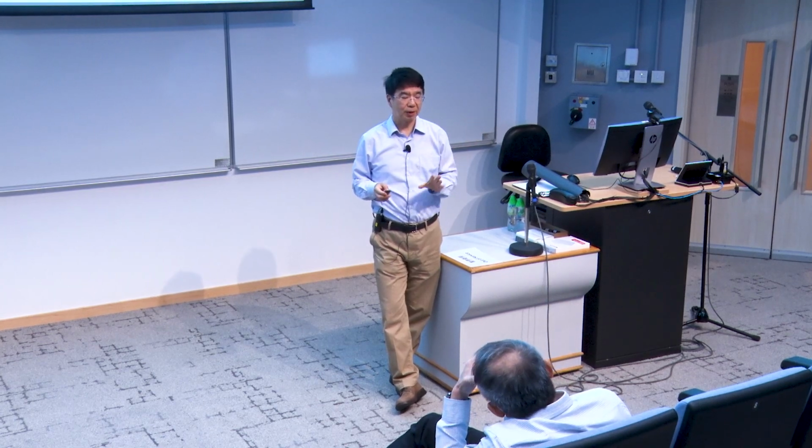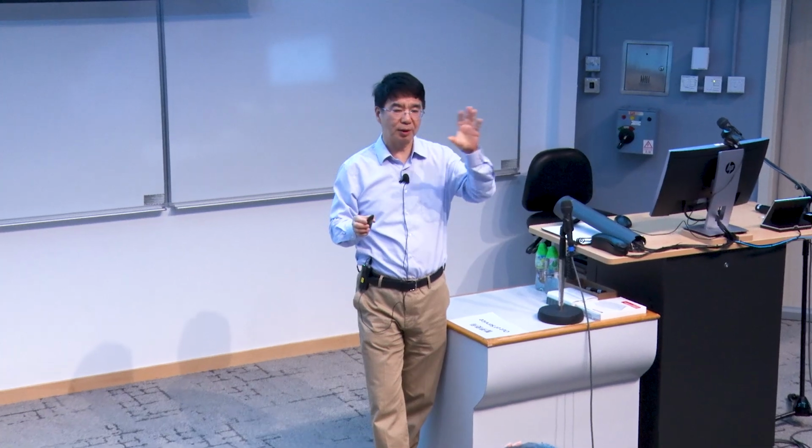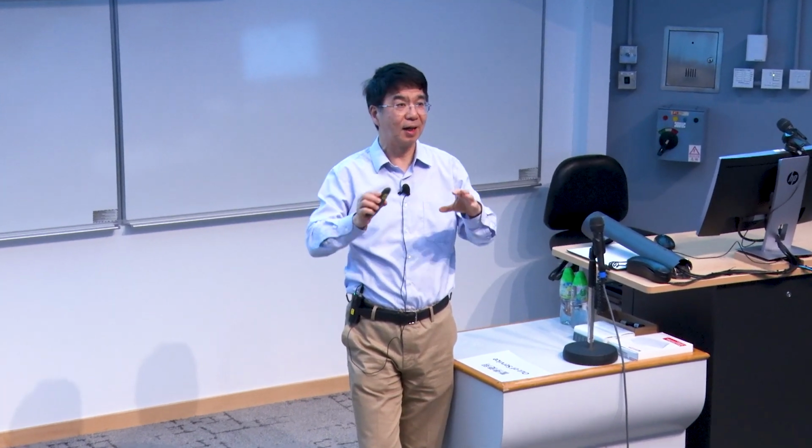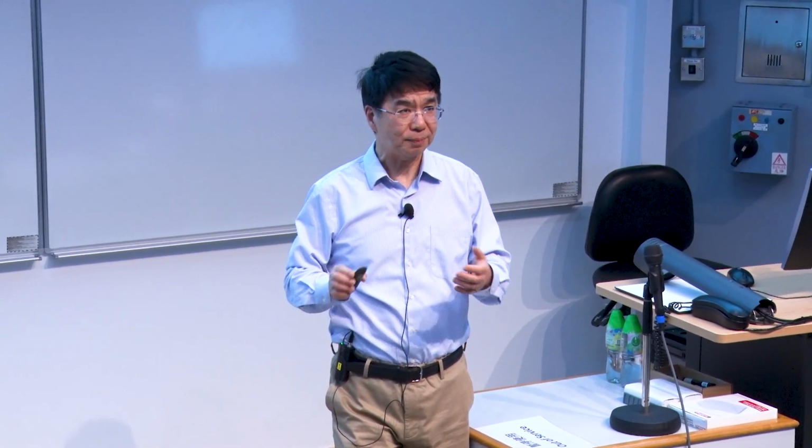Yeah, it's a very good observation. When you partition the design into regions, you want each region to be more or less balanced, and also not exceed its capacity, right? So we actually have a different set of equations or constraints, but that's done separately from deciding the number of registers, because you don't have to couple those together. The first one is a more classical physical design problem, so you can use the ILP to solve it.